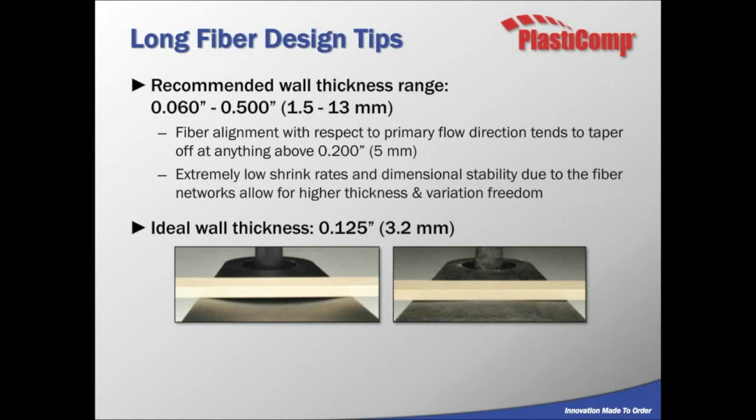Now, you can see at the upper end of that scale we have 1/2 an inch. Now, I don't really recommend using 1/2 an inch thickness, but the amazing thing is that you can actually get away with molding a part that thick. Now, it's important to realize that you're going to actually get diminishing return on the strength of the material itself the thicker you get. The reason for that is that you're not getting the same orientation as the part gets very thick. And when I say very thick, I'm talking over a 1/2 inch thick. So keep that diminishing return of strength in mind. But let's say you have organic reasons or ergonomic reasons, such as holding a handle. Maybe you need some thickness there just to make it a little more ergonomic. Feel free to do that, but realize it won't be quite as strong.